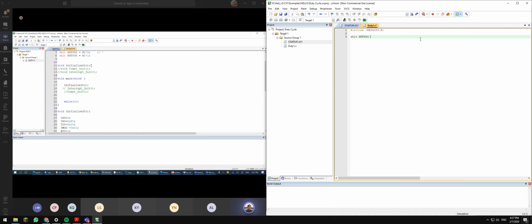So as usual, I do the initialization. I call the initialization function. Here I set the overflow bit. I set timer 0 and the timer 0 value FC18. TMOD is 0x01. Enable the external interrupt, the timer interrupt, and the master interrupt. The timer will start running. So it's very straightforward, basically.